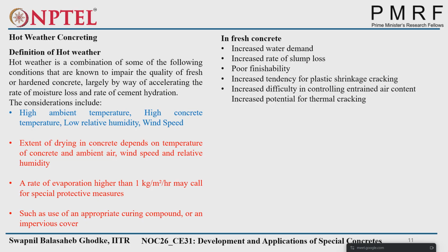right? Suppose you design the concrete mix for 50 MPa, and you keep increasing the water to get the same slump or same finishing of the concrete, you will lose the ultimate strength of the concrete. So we always have to take care of how much extra water we are adding. It should not be beyond the maximum limit based on the code conditions.